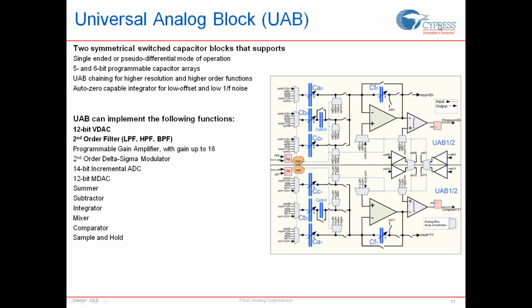Are all the blocks like the integrator and summer programmable? Yes, they are. Like I said, when it comes to implementing something like a summer, your programmability comes down to what capacitor values you have on the UAB, or what switching frequency you need.